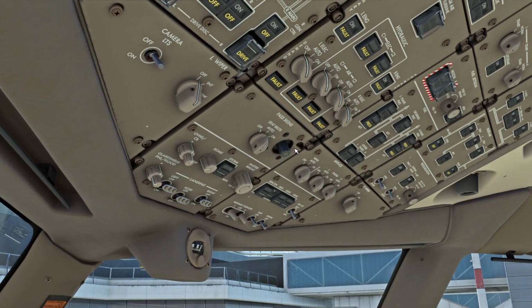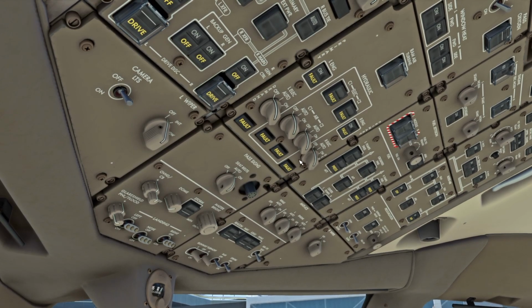Okay. So we're going to pressurize. The ground crew has installed a bypass pin, and this is important because before we pressurize anything, we don't want any nose gear movement or things that could hurt the ground people downstairs, because if you put on hydraulic power, it really has quite a bit of force. So a bypass pin needs to be installed in the nose gear in order to disconnect the steering tiller hydraulic force on the nose gear, allowing us to safely apply hydraulic power with the towing truck connected to the aircraft.